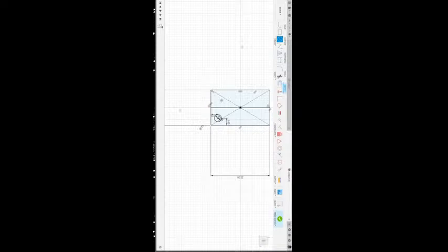Let's say we are going to design a gear. The gear might have 24 or 12 teeth. In that case you would use a pattern. If you're going to mirror 10 or 20 sketches, it's okay, you can mirror without issues. But if there are only 2 to 3 sketches at the same time, please do it manually. That will help you in designing it.